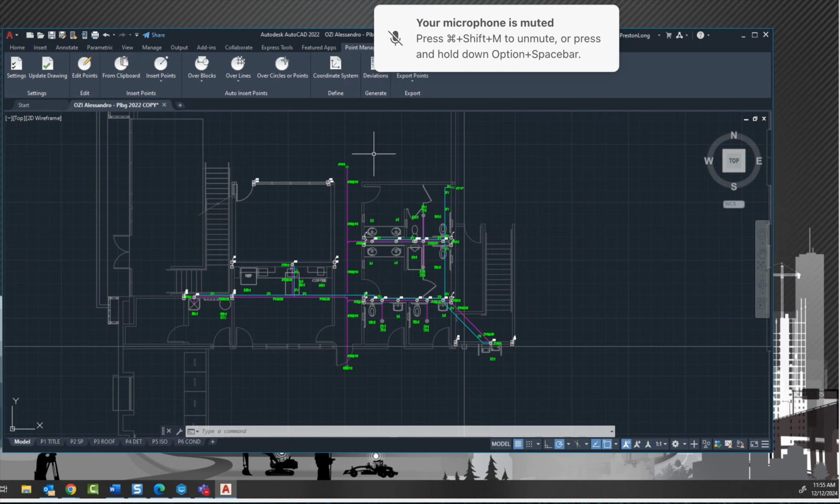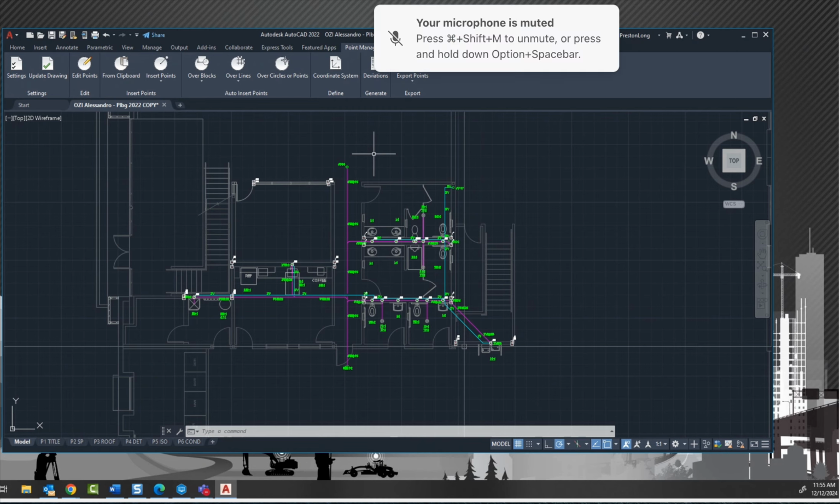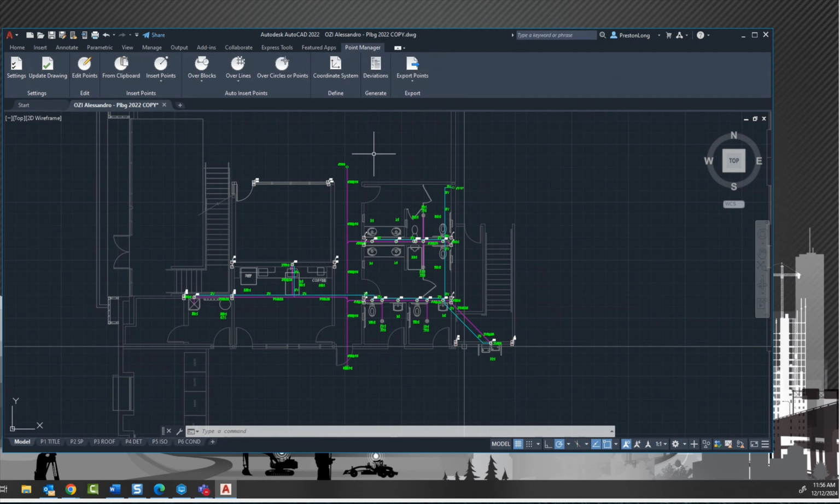Yeah. Okay, so that would come much later in the process, because you're doing your layout for your inserts before the concrete's even poured, right? And then after they pour the concrete and the decking, or it's sheet metal pan deck, they come back in and start throwing the threaded rod up and then setting their hangers that way. The total station guy's probably gone. Then you're looking at a drawing for those guys to install that, because there would be no notes for them to read. Yeah.